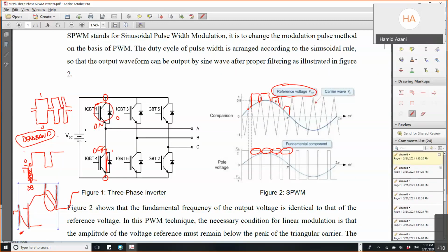So this part here is very critical and very important in practice, in order to avoid connecting the positive side of this DC battery with the other one, making them connected together. And this is what you call a sharp short circuit for this battery. So to avoid that, we have to take care of this dead band.